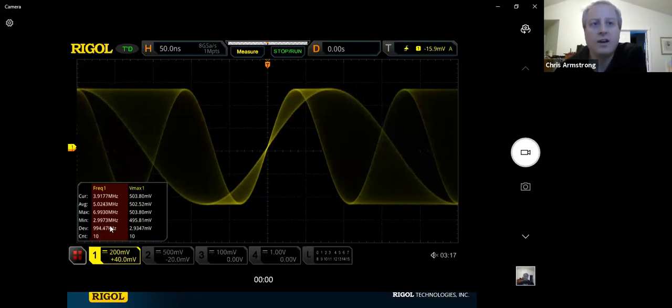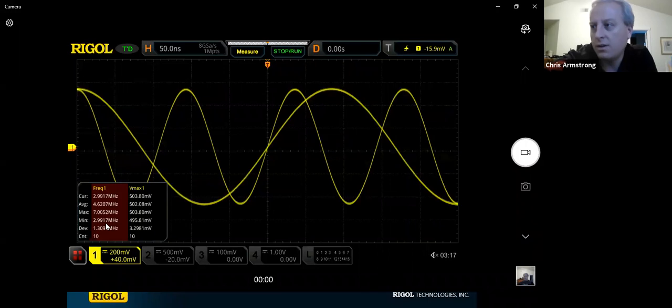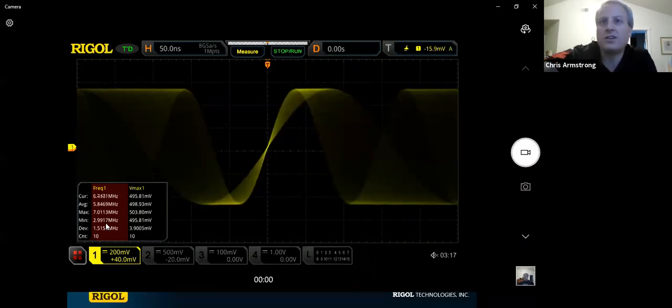And so we can see here the frequency changing between 3 and 7 megahertz, essentially. It's a standard sinusoidal FM modulation. Now, if I change the modulation to square type, then there's very little in between. There's just 3 and 7, right? Just moving fast between. You can see the different modulation schemes and how they look slightly different in the visualization on the scope itself.